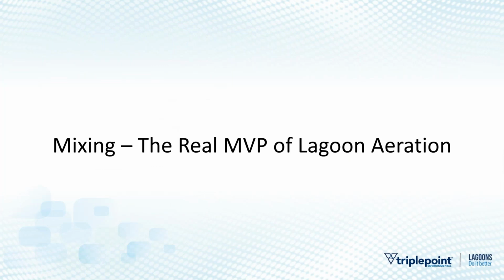So let's talk about mixing. That was all oxygen transfer, where we're getting air out there, but how are we going to spread it throughout the entire basin? We need to utilize your basin's volume. And mixing is extra important in the lagoon space because lagoons are a very, very large volume and they don't have full floor coverage of aeration.